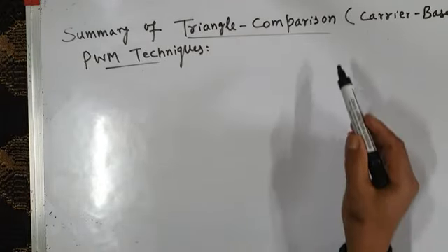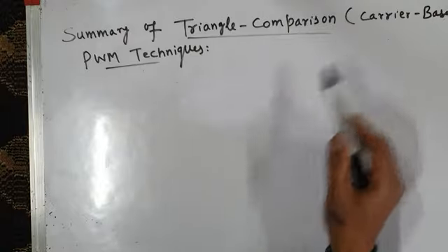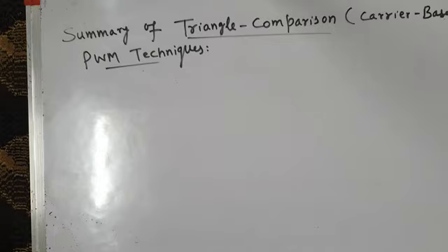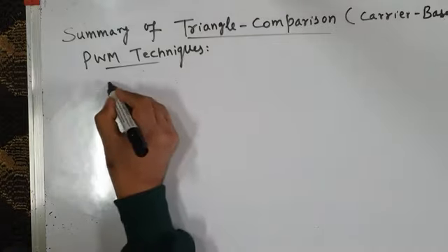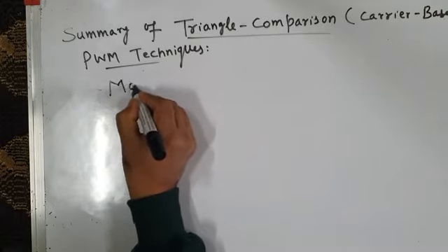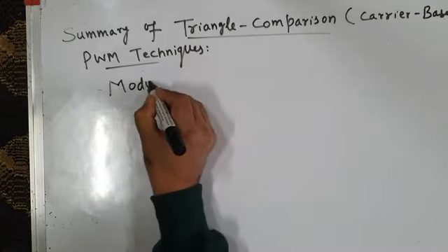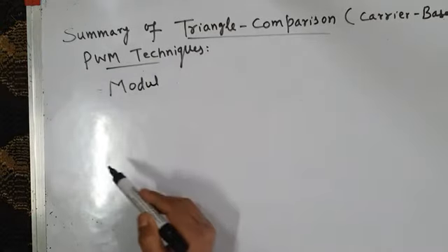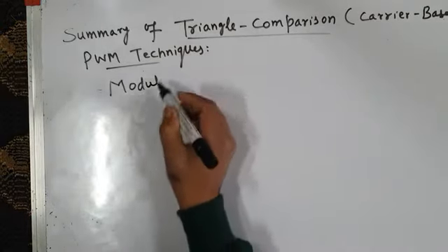Modulating waves have to be always compared with the triangular carrier. That's why these techniques are also called carrier based PWM techniques. That's the fundamental of triangle comparison based PWM techniques.